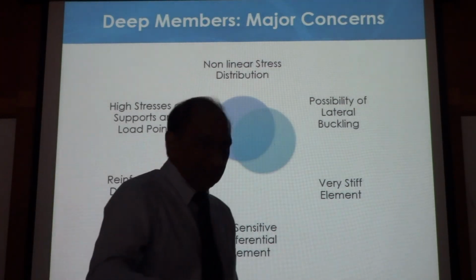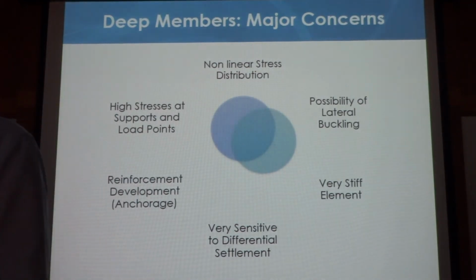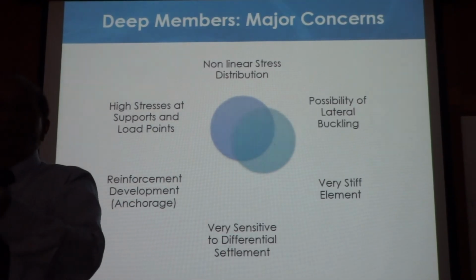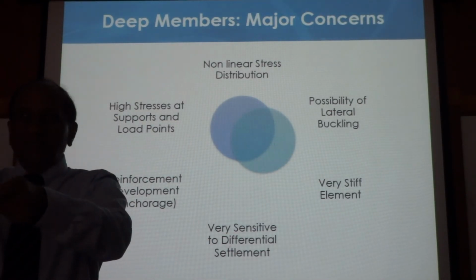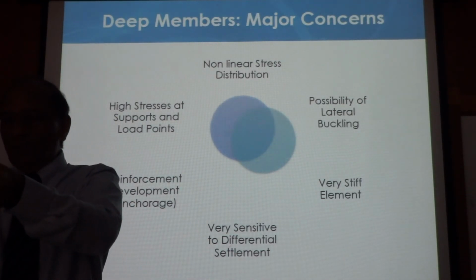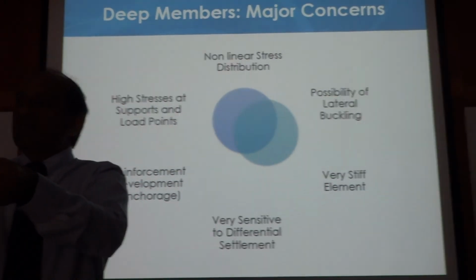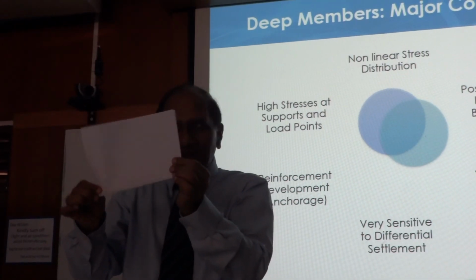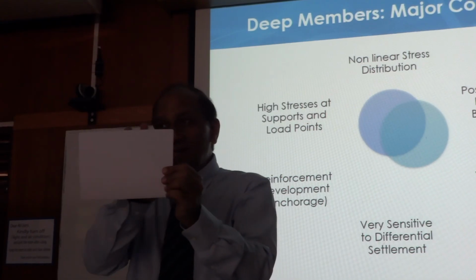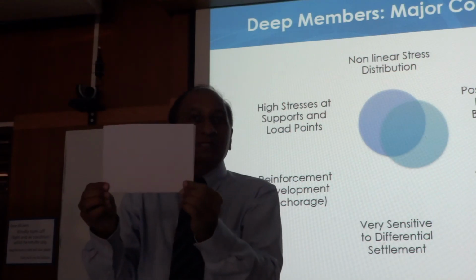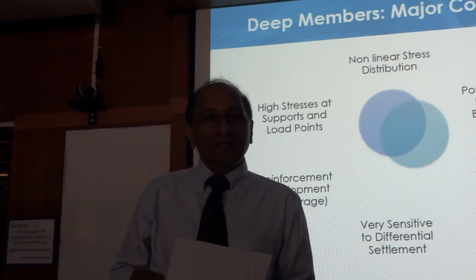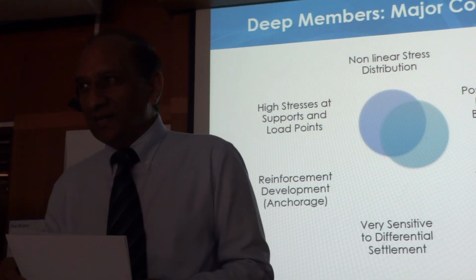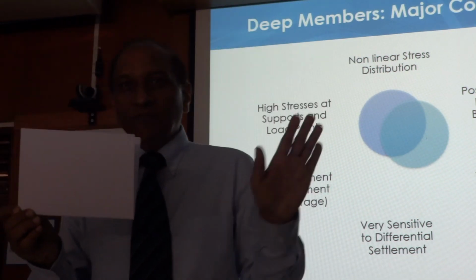If it is paper, can I have a paper? Okay, paper like this one, right? So no stiffness, I can bend it easily, right? No problem. So if I do like this, there will be hardly any stresses. The paper will just deform like that. If I do it like this, now if I try to bend even a little bit, it cannot. So very high stresses and many moments will develop because the stiffness is so high, and deformations are related to stiffness, correct? So small deformation produces a lot of bending moment.